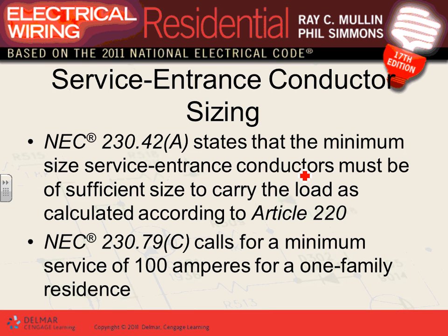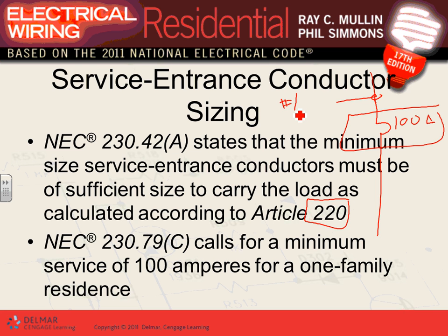Okay, service entrance conductor sizing must be sufficient to carry the load that's calculated. So how do you size a service entrance conductor, guys? Piece of cake. When you went for 100 amp, here's my service disconnect means, 100 amp, and you went to size this conductor, you went to 310.15(B). Can everybody go there, guys, to 310.15? (B)(7), that little table for the commercial, and was it number 1? And we use number 1/2 conductors plus, of course, the neutral.